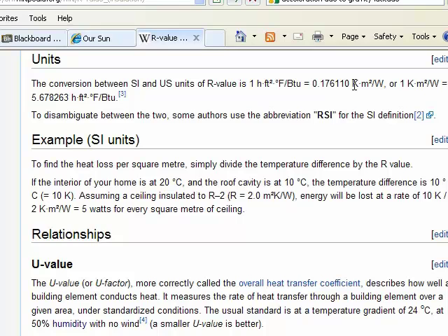Notice the units here, the kelvins. It's of course the same as the Celsius degrees. You saw the square meter in there, and then the watt is the same as joules per second, and that is then transferred into these units which are underlying the R value.